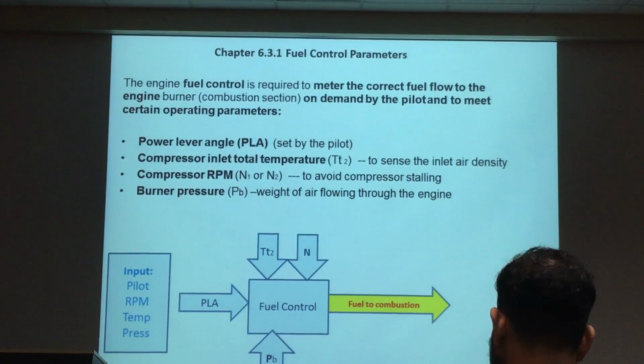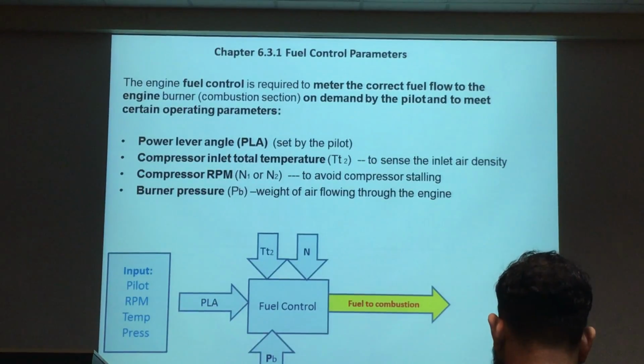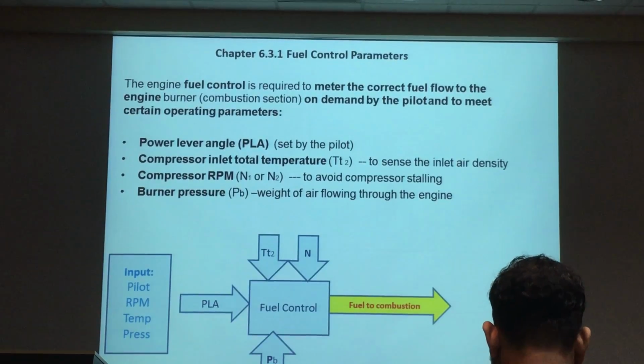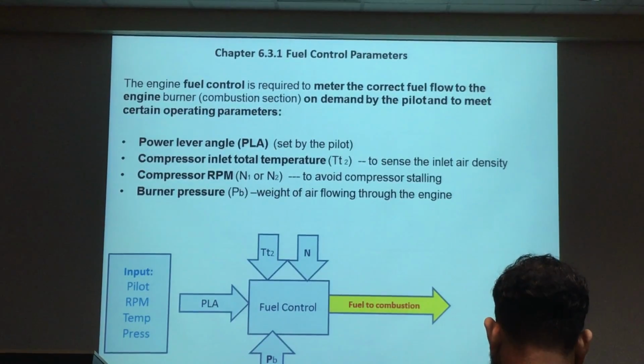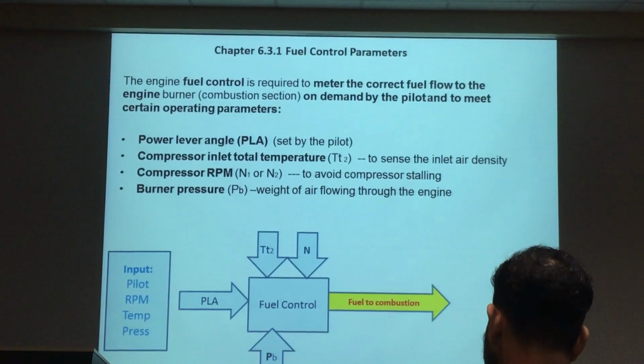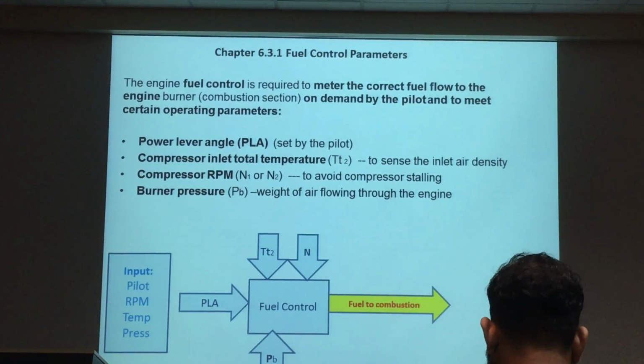Okay? The next one is your burner pressure. Burner pressure is your diffuser pressure. Diffuser pressure does not have such high temperature, so it's easy to measure. Okay? If you go and measure combustion chamber pressure, it's difficult. So they measure the diffuser pressure. Okay?